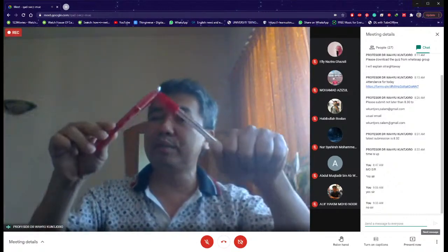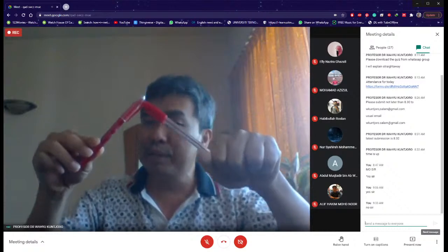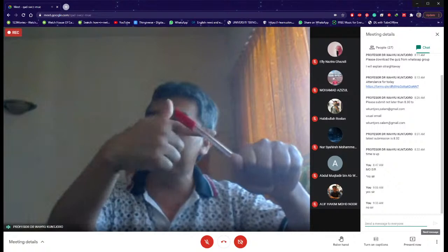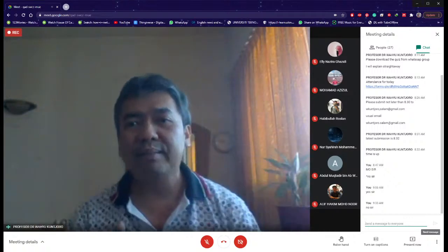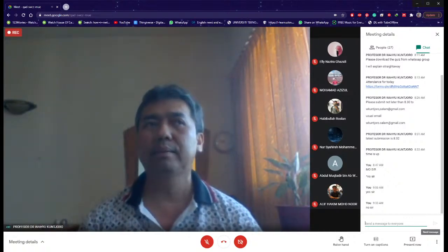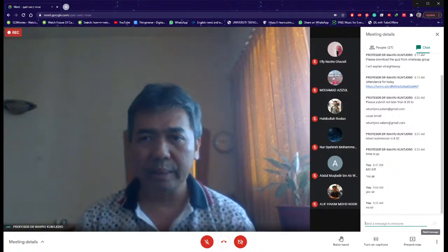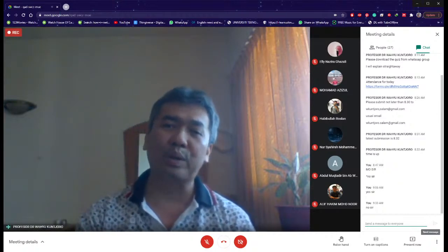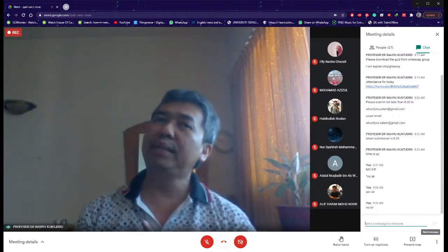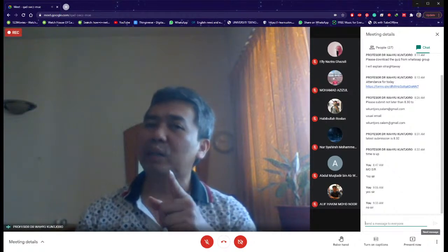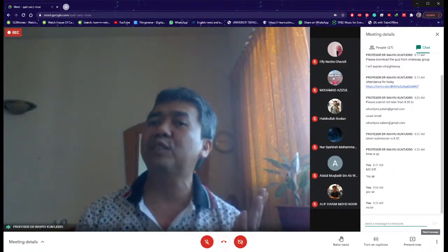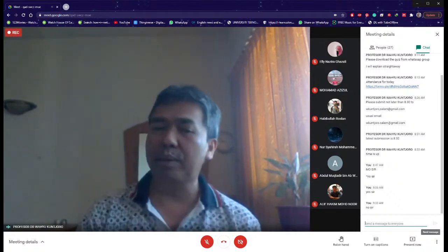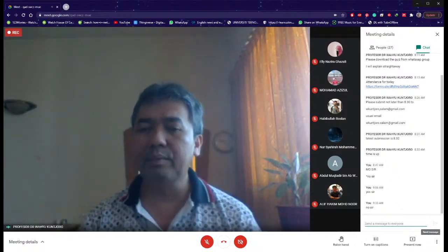But once that connection is pin joint, then you have truss, because now the force is in X and Y, but the resultant is still axial. That's why if you look at the theory, in the book or in the slide, we got the truss element equation by transforming the bar, doing vector transformation. So by now I hope you understand what truss is.